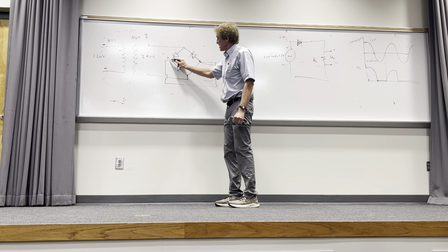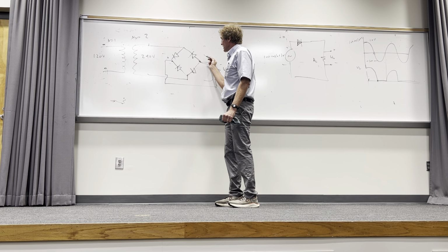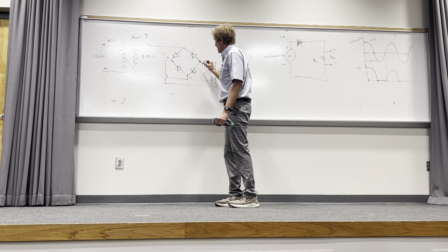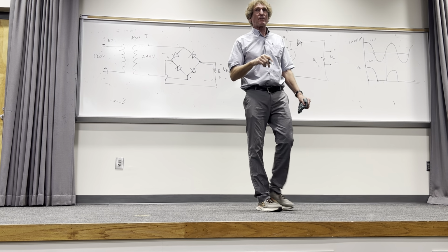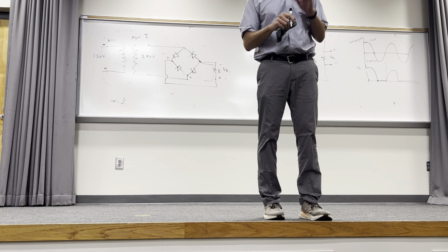Basically, it would flow here, here, and then here. It can't flow that way, it's going against the arrow. Then when it flips, when this becomes negative and this becomes positive, all the current will still flow in the same direction and you'll get full wave rectification. You will appreciate this once you go through some. This is an ideal diode.